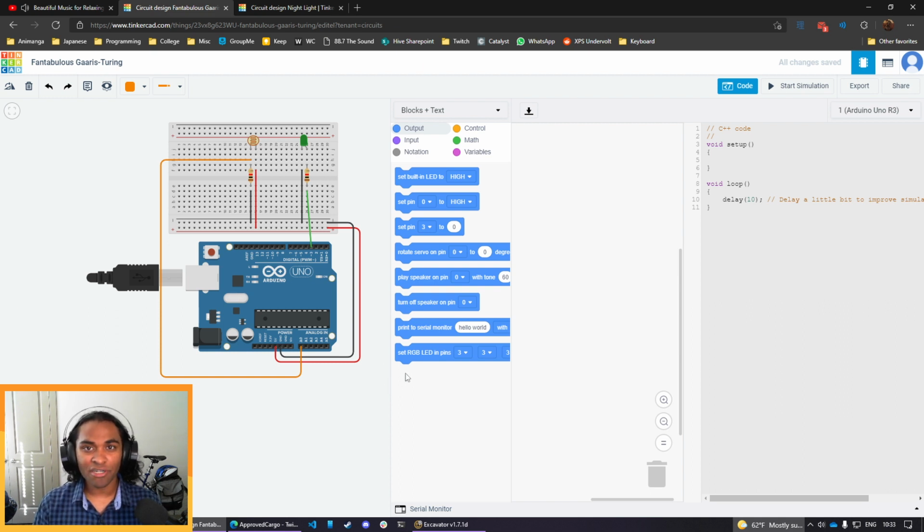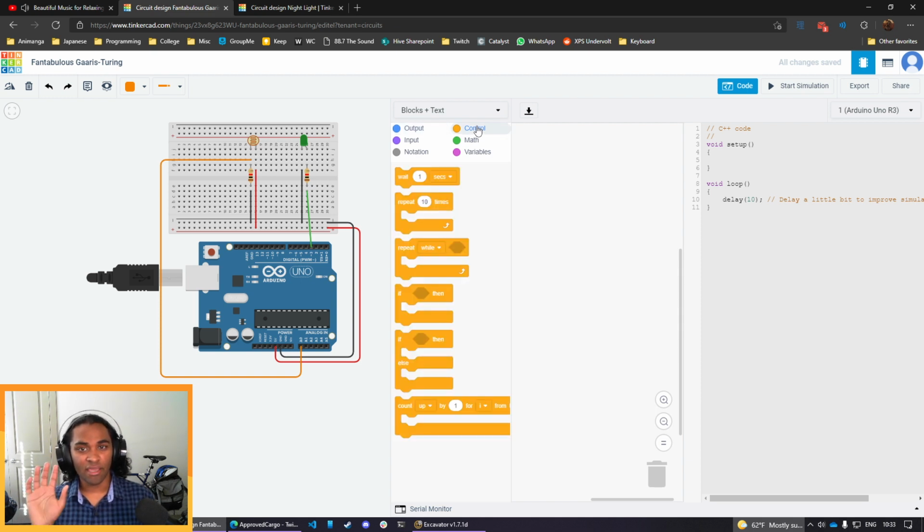So how we're going to simulate that is think about the control flow here. So we said, okay, this is the key word, right? If our value from our photoresistor is less than 512, then turn the light on. Otherwise, or else, that's another key word. So if and else, right? So else, otherwise, if that value is equal to or greater than 512, just making an inclusive range, then we are going to turn our nightlight off.